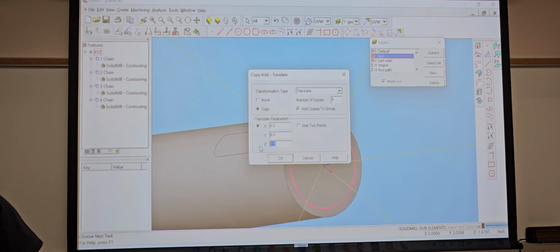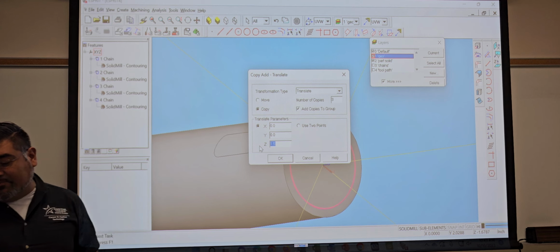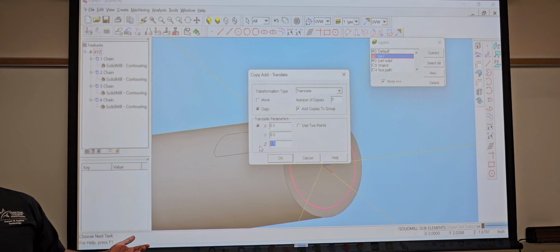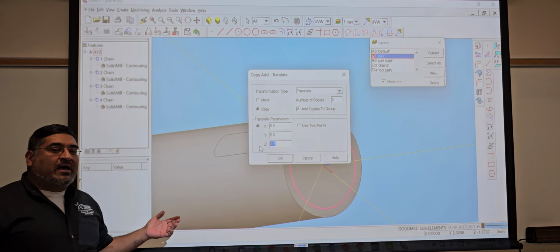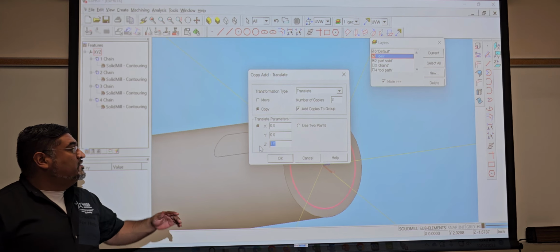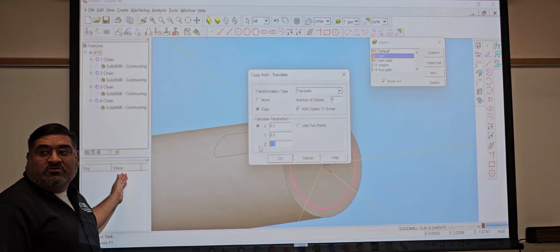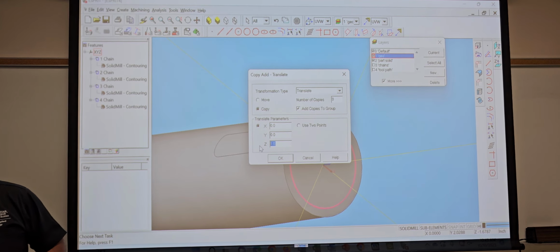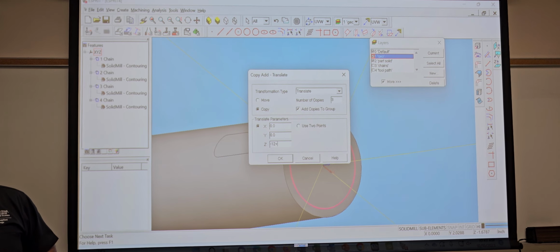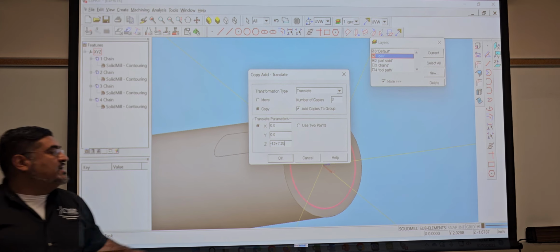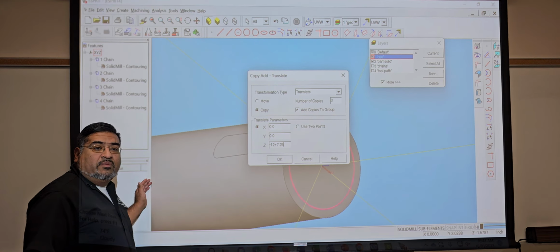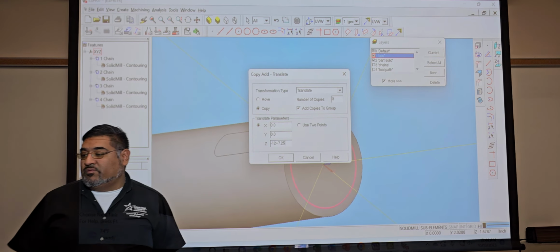So from Z, obviously I look at my print and it's backwards, right? So we would have to do the math for it backwards, or I could just say, hey, Z is gonna be negative 12.7, plus 7.25, correct? So that's gonna already take it to Z negative, but then it's gonna add the 7.25.